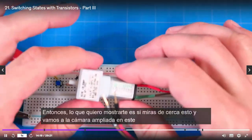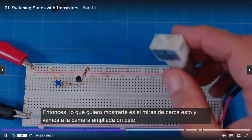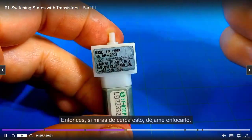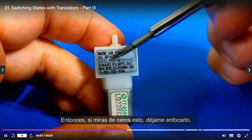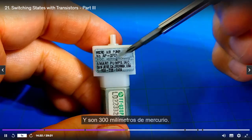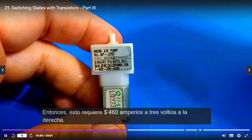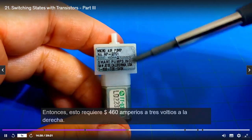All right. So what I want to show you is, if you look closely at this, and let's go to the zoomed in camera on this one. So if you look closely at this, let me get it to focus. It says 3 volts DC at 460 milliamps, all right? And that's 300 millimeters of mercury. That's the pressure that it can pump at. So this thing requires 460 milliamps at 3 volts, right?